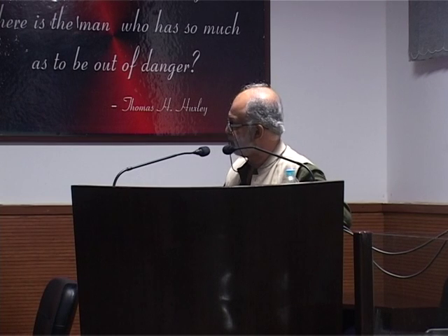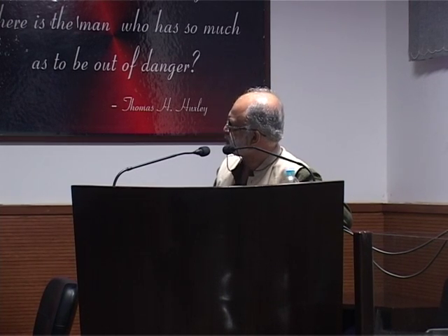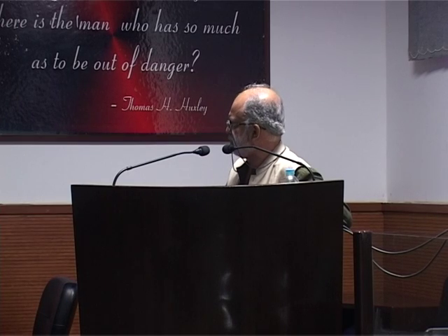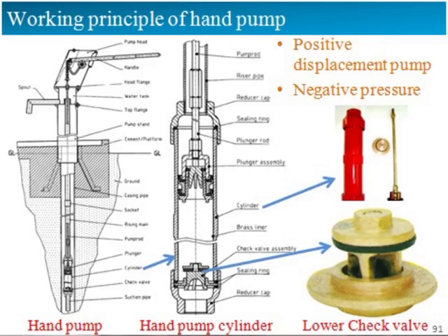That's precisely what was done out here. So what was done is this particular hand pump, and this is the bottom wall of the hand pump. This is a device which keeps, this is a load check valve, and this disc keeps on moving up and down depending upon the stroke of the pump which you give.